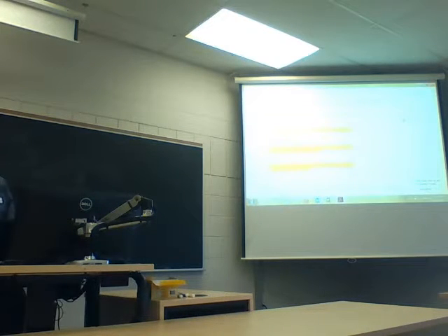The stator of the casing? Stator of the casing, yes. This uses a positive displacement compressor? It's definitely a positive displacement compressor, usually in a screw type. So it's usually a control device, right? Yeah. On a reciprocating compressor, we usually have something called an unloader. We'll unload the intake or the exhaust valve, usually one or the other, not both of them. This one here will actually just circle. What's the word? Going around and around. Yeah, okay. Thank you. There you go. You don't have to speak English to be an engineer.